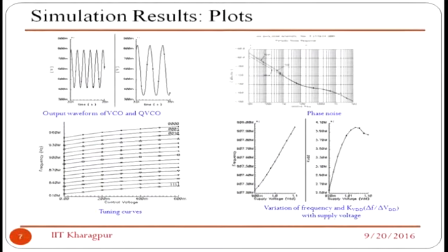Now coming to the simulation part. First of all, you have to look at the transient simulations. Once you start the transient simulations, you see how the oscillation builds up. Initially you will find some small undulations, and then finally it starts. The point where you have the equal amplitude, from 0, is called the transient time, that means the settling time. So the settling time should be as small as possible. That is an important criterion to build up oscillations.